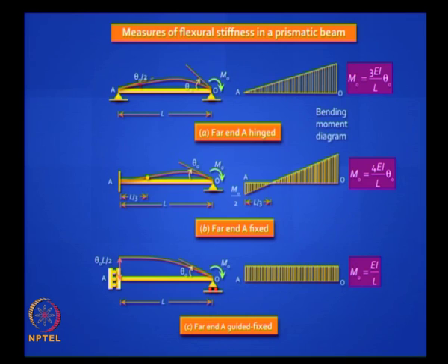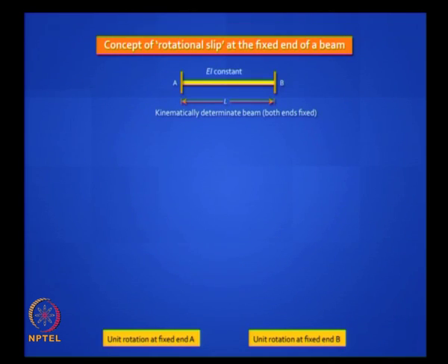and this is pure bending, the last case, so you have a uniform bending moment diagram. So these 3 are worth remembering because you can take a lot of shortcuts if you can invoke this understanding. Traditionally you arrest all degrees of freedom in the displacement method and get your primary structure, but if you can modify those stiffnesses for these 3 cases, your degree of indeterminacy drastically reduces, and we want to take advantage of that.